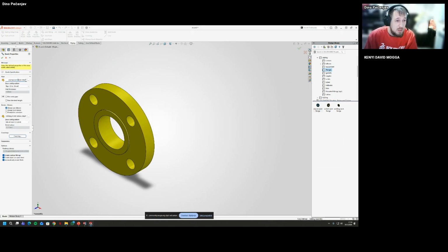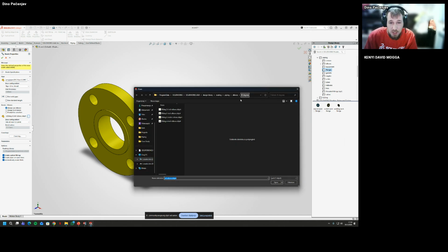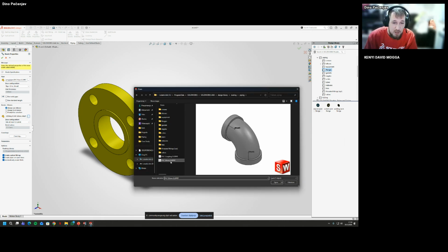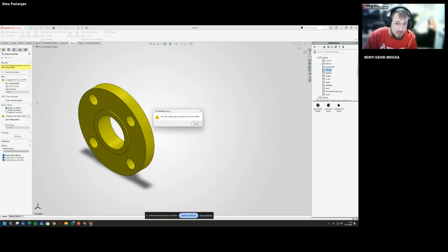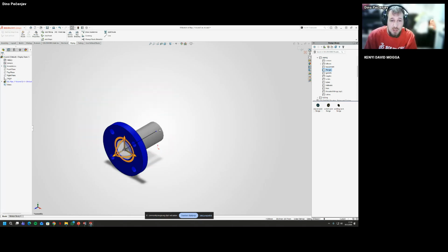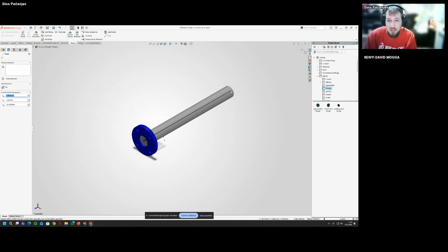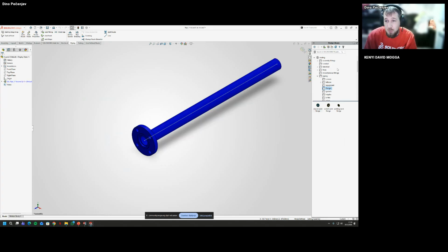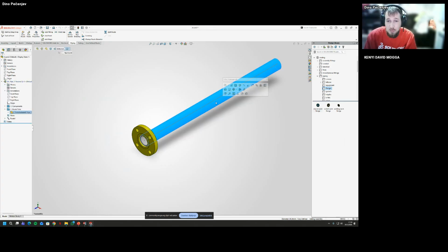Okay, I'm going to change the pipe I'm using, and I can change the elbow I'm using. It's piping, so I can change the location of this later. Because it doesn't have a configuration, I cannot use these elbows, but just for the sake of showing how it's created, since we have at least the coupling. When this is created and the size is changed, the color also changes. So you change the colors in the components.